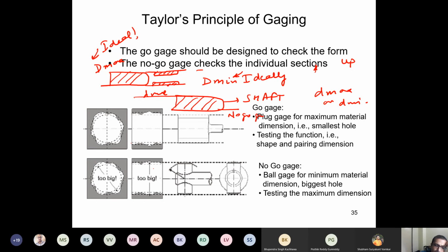Now again, the tolerances you will do the same thing. If you want to ensure that there are no defective pieces, then you eat up some good pieces. You can basically reject some good pieces, but you don't accept one bad piece. So that's how you set tolerances on the gauges. When I give you the homework, I'll give you a problem for that.